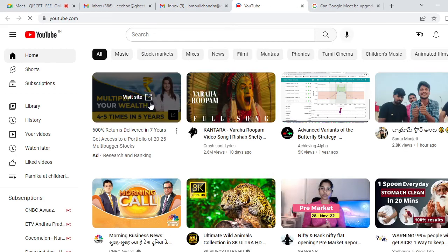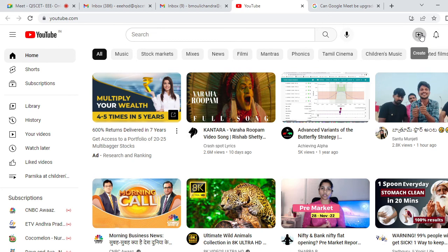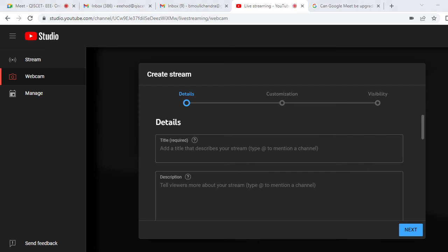So here also you can see that if you have more reactive power loss, then you have to manage the reactive power to improve the voltage profile as well as the voltage stability index. You can utilize some FACTS device, you can utilize some capacitor, so these are the options you can do. That is why in modern power systems we are utilizing some devices, but cost is also one important part.